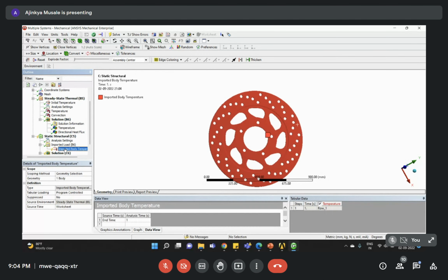So same thing like our yesterday's pre-stress calculation. There, I was doing my modal calculations, but with results of my earlier static structural calculations. In that, I had some loads. Due to that load, some stresses were generated in my model. So that stressed model I used for calculating my natural frequency.